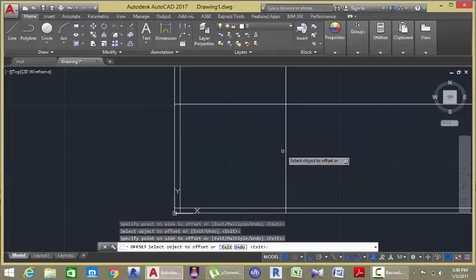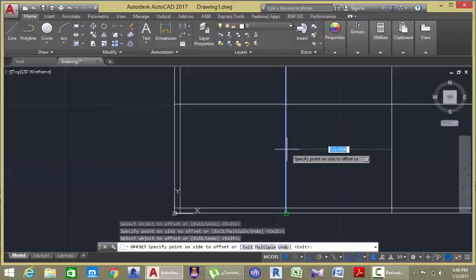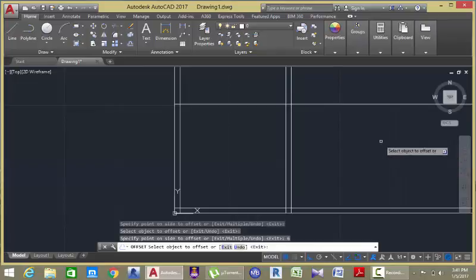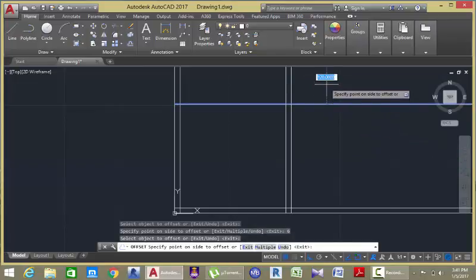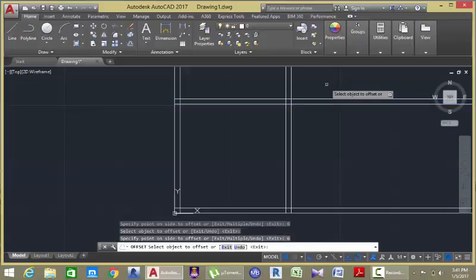Now, if I select this vertical line that I just offset, the third one, then I move to the right. AutoCAD still remembers the 120 units measurement that I entered, but you can override this measurement. Now, if I type 6 on your keyboard, as you can see, the 120 is gone. Now only the 6 that I typed is in the input. Now press enter. AutoCAD offsets the object 6 units. Do the same thing for the vertical line. Type 6 units and press enter.